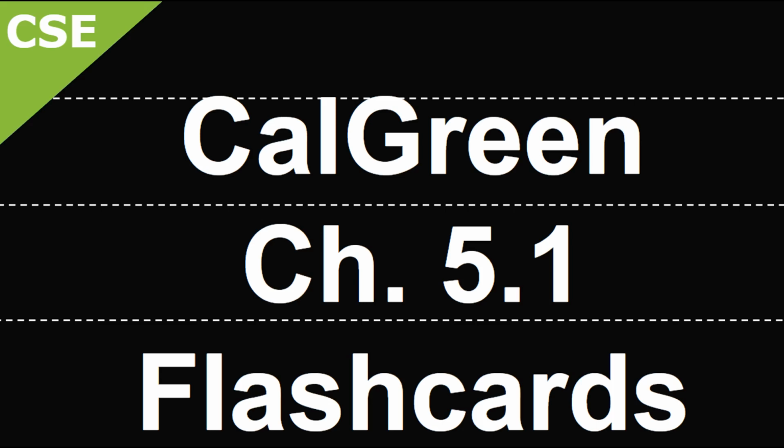If you're providing 51 to 75 total actual parking spaces on a new project, then 13 are required to be EV-capable, and of those 13, 3 are required to be electric vehicle charging stations. If 76 to 100 total actual parking spaces are provided, then 17 must be EV-capable spaces and 4 EV charging stations of those 17. If 101 to 150 actual parking spaces, then 25 are required to be EV-capable, and of those, 6 must be EV charging stations.